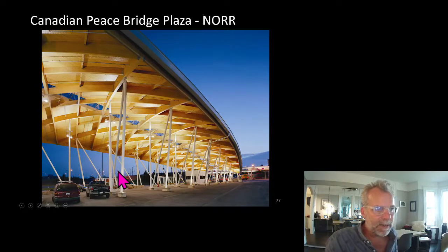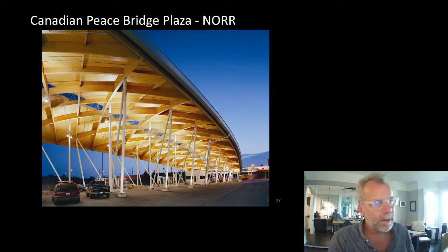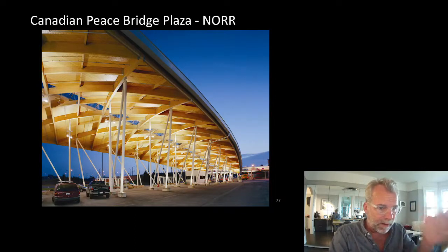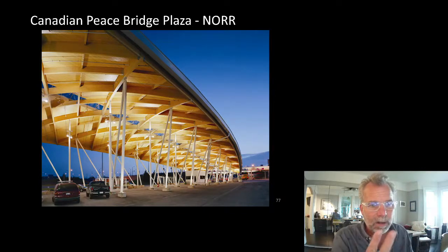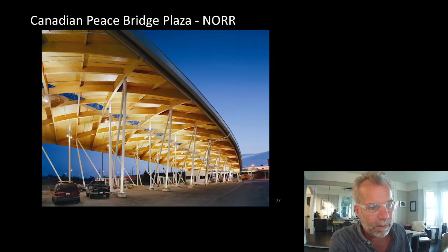In this project, you can see there's only bracing in one direction. I wonder what carries the lateral loads in the other direction. But in fact, it's herringbone. So the bracing is parallel to this element here, but on the other side, it's parallel to that element. So we need bracing to resist loads in both directions, but it doesn't have to be the principal direction. It doesn't have to be parallel to longitudinal and cross axis. As long as it's two non-orthogonal axes, we're fine. So in this case, we oriented our bracing on a herringbone, and that gave it stability in both directions.